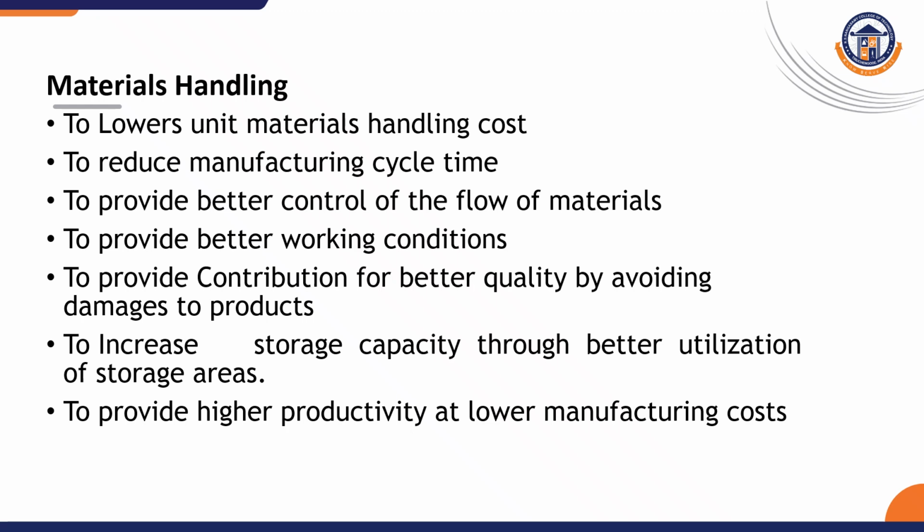If you want to reduce the time, your material handling equipments, the forklift trucks, cranes, hoists, whatever you are using, must work efficiently. So that is all interlinked. Then to provide better working conditions, yes, you should not allow the worker to lift weight. You must allow the worker to guide that weight through equipments and store it in proper places. Then to provide contribution for better quality by avoiding damages to products. Very important.